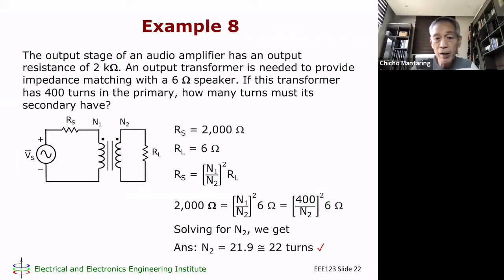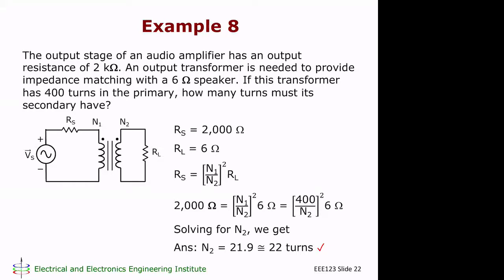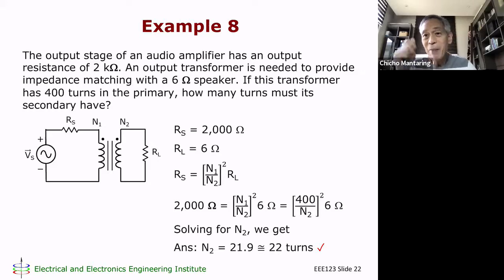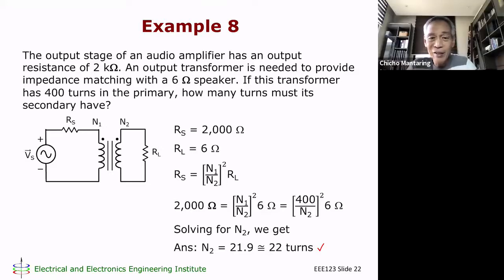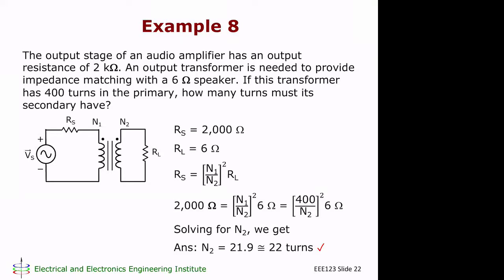So there's a question. Can you just ask your question directly, Rick? Do we always round up the number of turns? Well, it's difficult when you're winding a transformer to make it exactly 21.9, right? So you have to be practical. So just make it 22, no? But is the rounding, round up po ba palagi? Actually, not necessarily, no? Not necessarily. Okay, thank you.